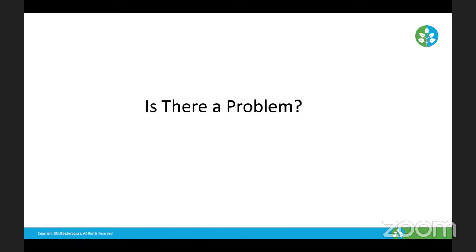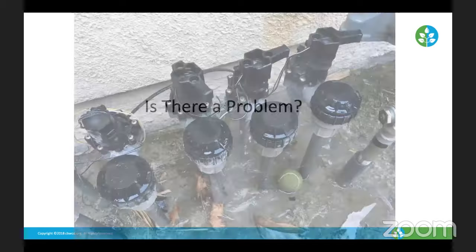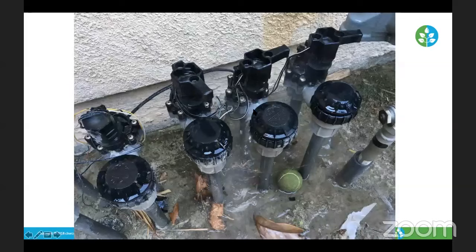Depending on the type of valve you have installed at your residence, or let's say if you're managing a site, depending on the brand and the model, some replacement parts are a lot easier to find than others. So here's an example. This was a picture taken at one of our evaluations. This is the valve that I took apart. When the valve runs, water is leaking from this part of the diaphragm. Where the diaphragm meets with the body, underneath there, the diaphragm just worn out in that spot, and it's causing all that leakage.